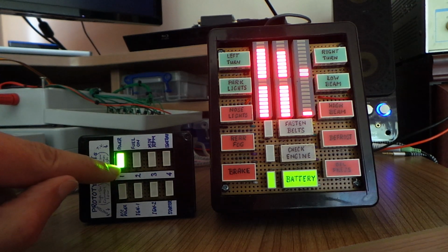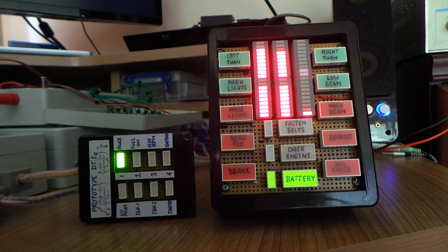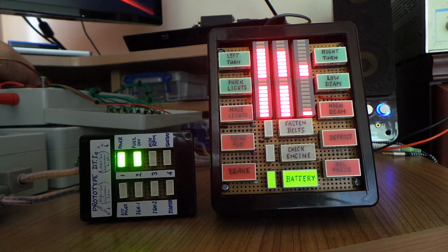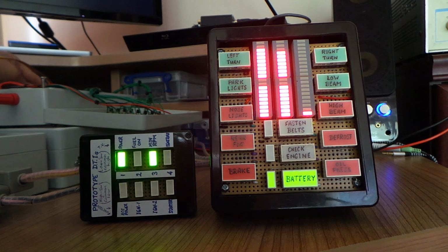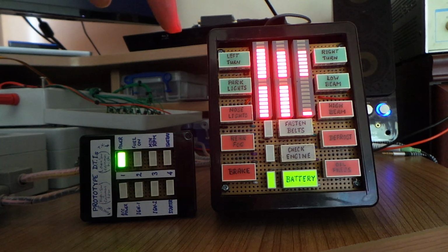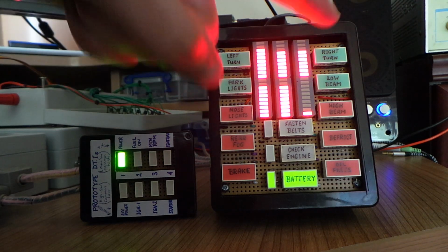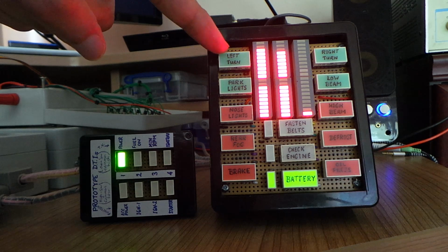The dashtop indicators are exactly the same, indicating power is connected, indicating primary ignition power on that one, indicating secondary ignition power on that one, and indicating the starter discrete on that one. Let's just switch those off again. Notice that when we're in input test mode, the display mode for the side indicators is always the normal mode. We don't want any flashing in this mode. We want to just see that they're responding.